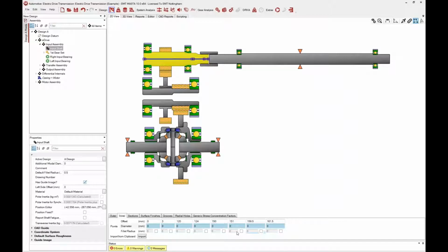The same thing applies with checkboxes as well. So let's say I wanted to actually apply a fillet radius to all of these at once, for whatever reason. If I select all of those, if I enter a value in there, it will activate those. And I can click on the enter key to actually apply a value in there. It's not doing it in this case because of my specific geometry. However, the spacebar will activate and deactivate these, and then I can add in a value.